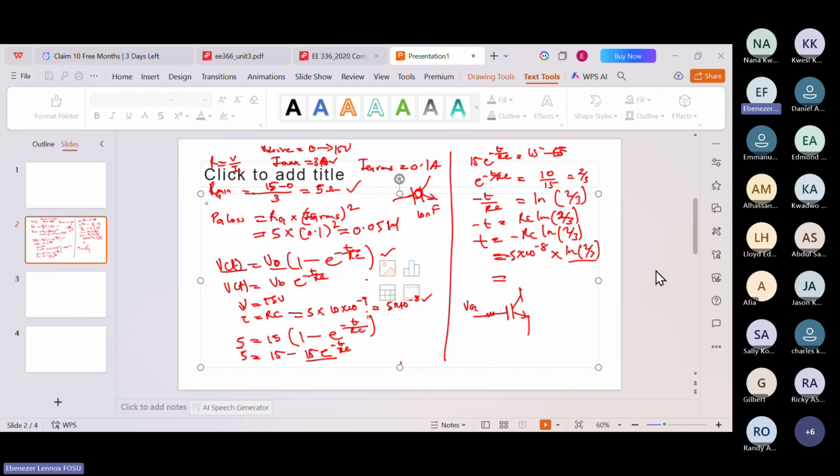All right. So this should be in seconds. That is what you will get, as this is the time it takes for the IGBT to turn on, for the voltage to rise up to the threshold voltage before it can turn on. So that is the A part of the question. It was just focusing on the gate. Now let's look at the next question.